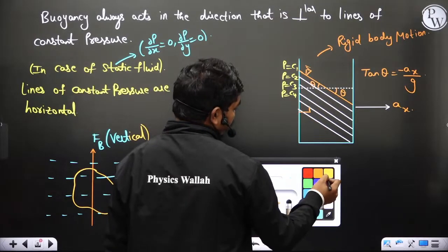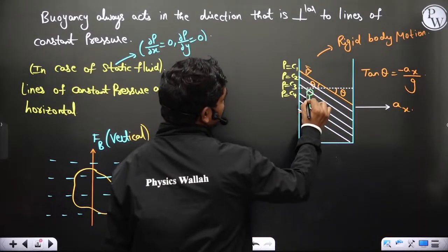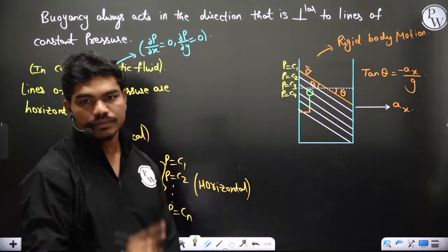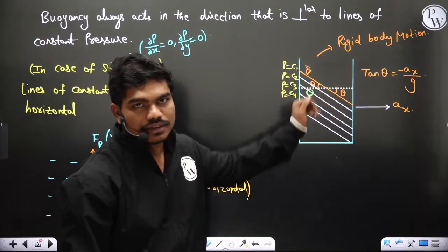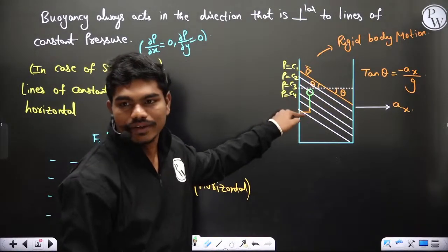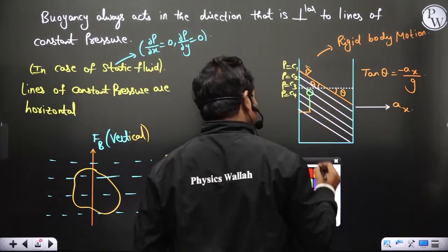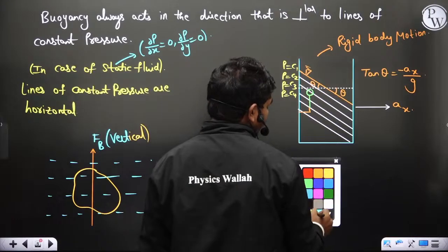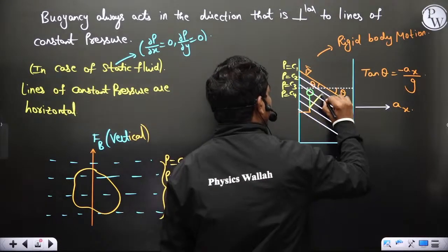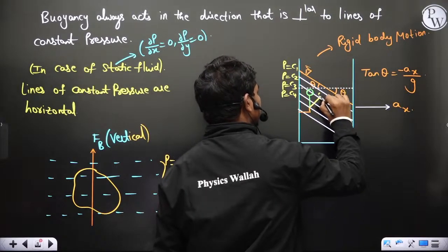Okay, so you take a balloon and you attach it here. For example, if you have a balloon here, initially the balloon will be floating vertical, yes or no? If the tank is in static condition, the balloon will definitely float in the vertical direction, and this string has to have a tension. Now similarly, when this tank is accelerating, this balloon will take a new orientation, which is something like this, because this balloon is actually pushed in this particular direction.